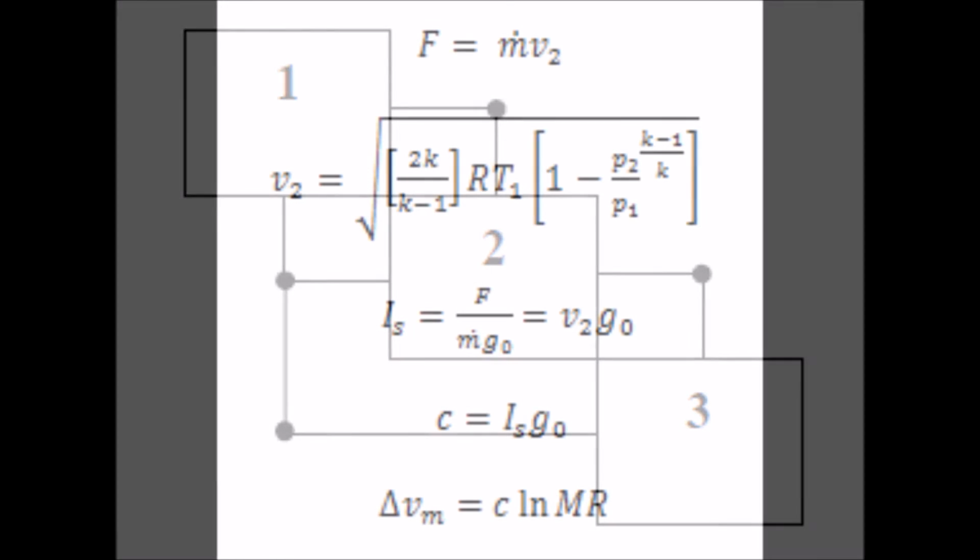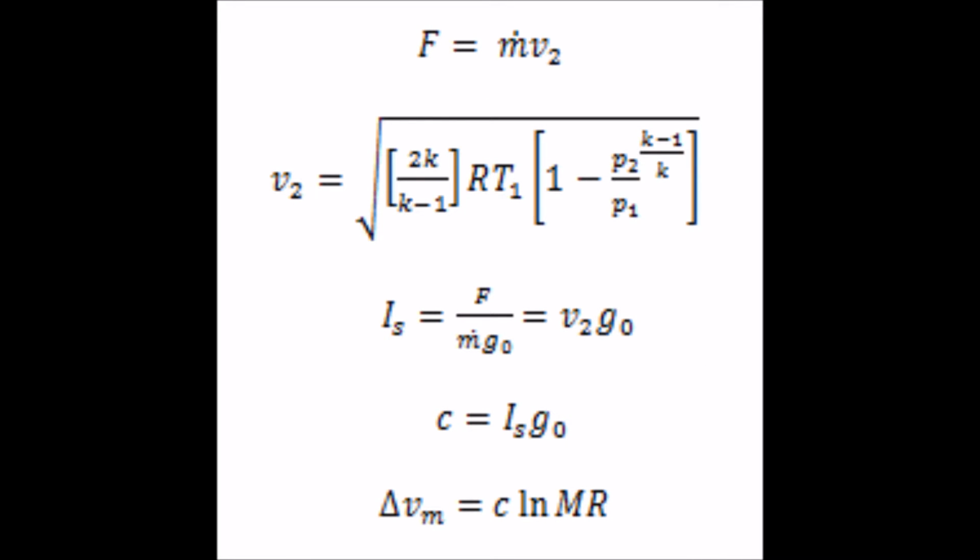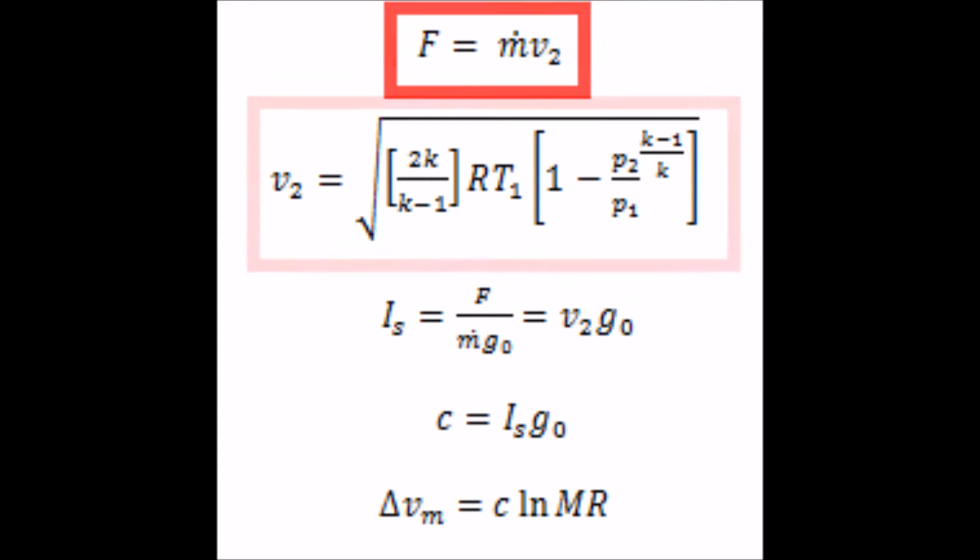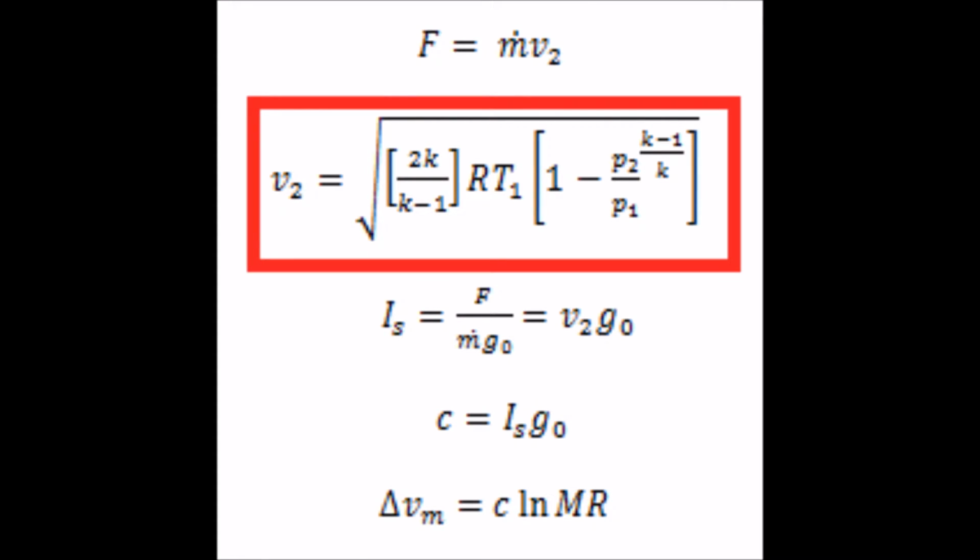Next, we look at the equations of the device, describing the behavior of the system, utilizing characteristics of the subsystems mentioned. Here you can see the thrust dependent on mass flow rate and exhaust velocity. This is assuming an optimally expanded nozzle. The exhaust velocity is dependent on the specific heat ratio of the propellant chosen, the pressure ratio, and the chamber temperature induced by the cathode.